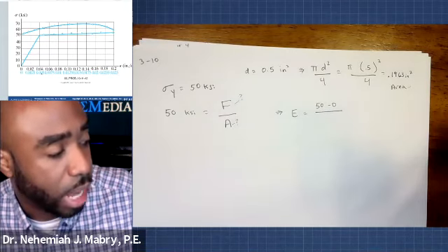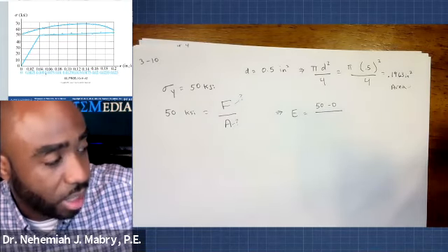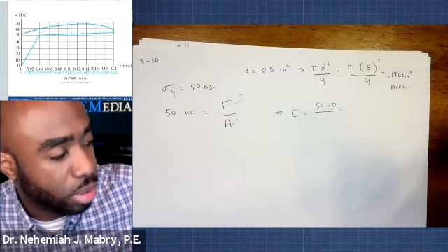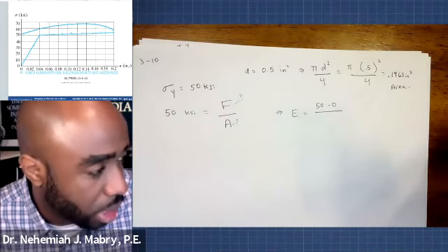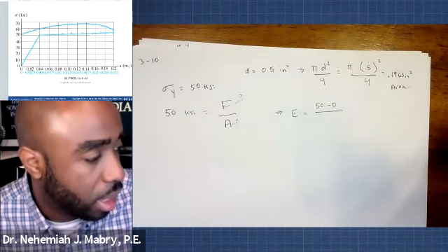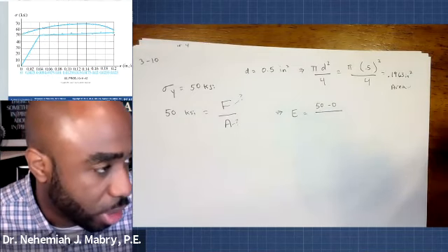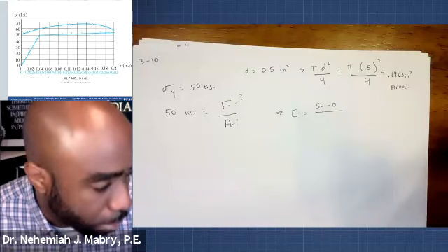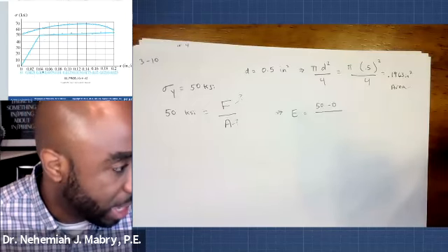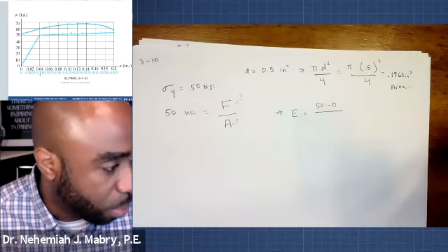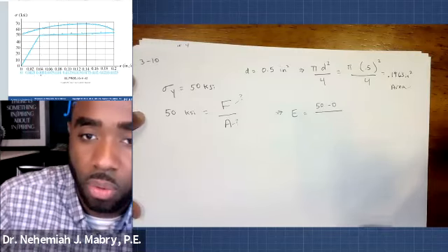And I'm sorry, let me tell you something. I actually told you something the opposite earlier. So these light blue numbers are actually the numbers that go with our bottom portion, not our top. So the top portion has larger strain values because, again, we're imagining it's on this side. So the light blue is going for this. So what we see right here is at 50 KSI, it is experiencing a strain of 0.005.